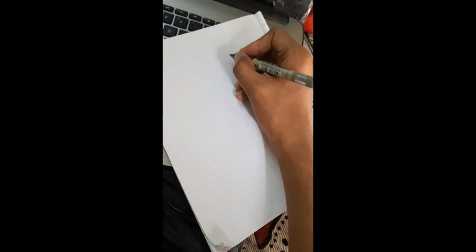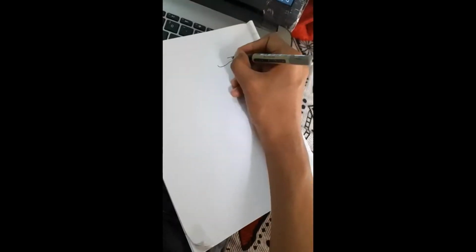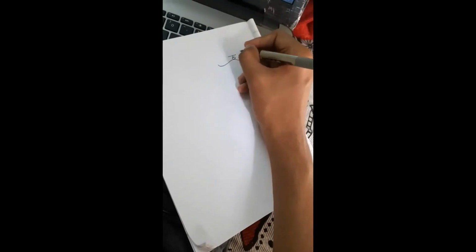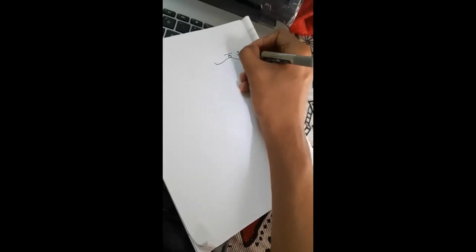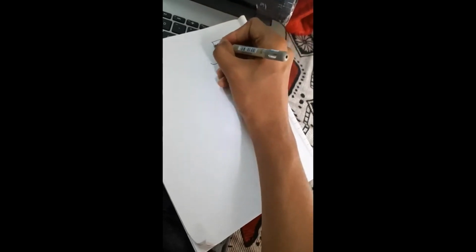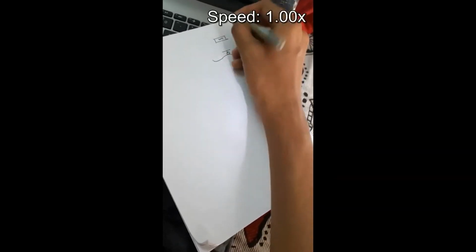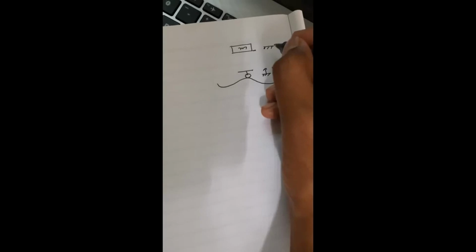This is the basic thing you need to know before starting to make a model of a quarter car or half car model. So let's suppose this is a road emulation. From the bump, the displacement and the force are going to transfer through the wheel to the sprung mass of the body. Suppose the displacement y is there on the tire, and similarly the thing we need is the displacement of the sprung mass, that is m, that is x here.